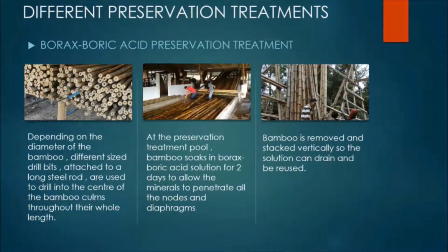To enhance its natural durability and to protect it from insects, it is necessary to treat bamboo before use. For construction use, mature bamboo between 3 to 5 years old is selected. It shrinks less when dry and its starch and sugar contents are low, so there is less chance of insect infestation. Different species of bamboo have different uses.